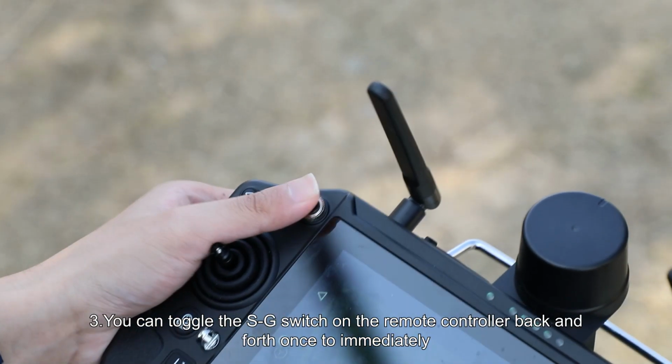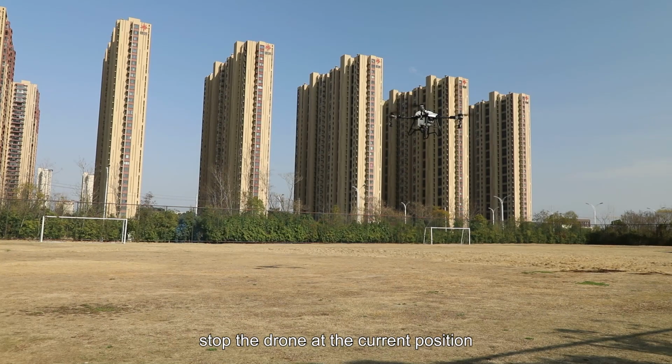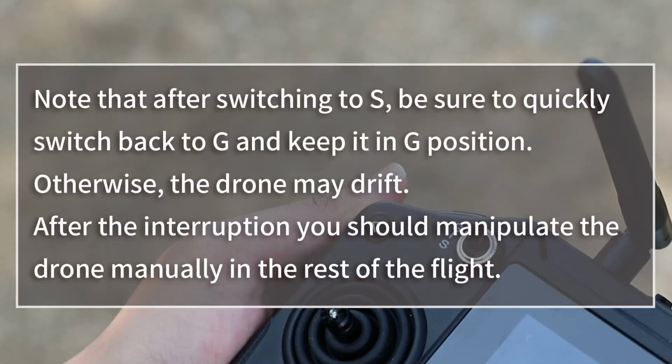3. You can toggle the SG switch on the remote controller back and forth once to immediately stop the drone at the current position. Note that after switching to S, be sure to quickly switch back to G and keep it in G position. Otherwise, the drone may drift. After the interruption, you should manipulate the drone manually in the rest of the flight.